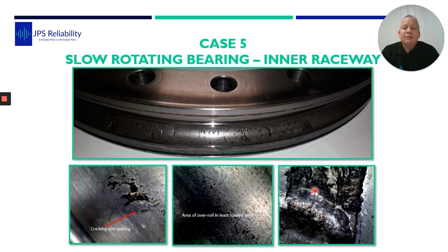Cleaning up the bearing, and there was our inner race as we expected. Some lovely craters all along here, and it was more one part of the bearing, one small section of the bearing would have gone more than the rest. You can see here the cracks are spawning, so this is like it's got overroll or subsurface fatigue, and it's cracked and starting to peel up.